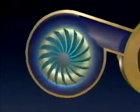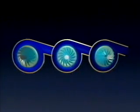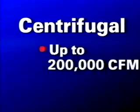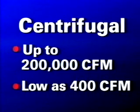Usually, 2 or 3 stages are used to achieve a compression of 125 pounds per square inch gauge. Centrifugal compressors are often thought of as high-volume flow machines, with capacities up to 200,000 cubic feet per minute. In recent years, however, new designs achieve flows as low as 400 CFM.